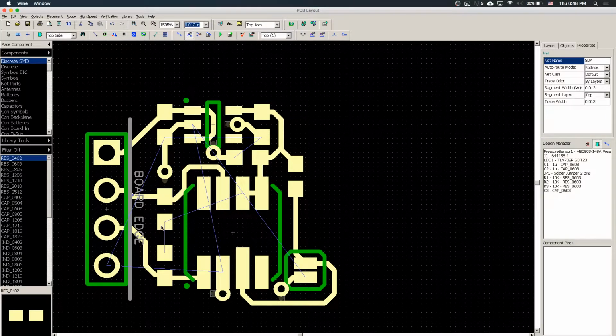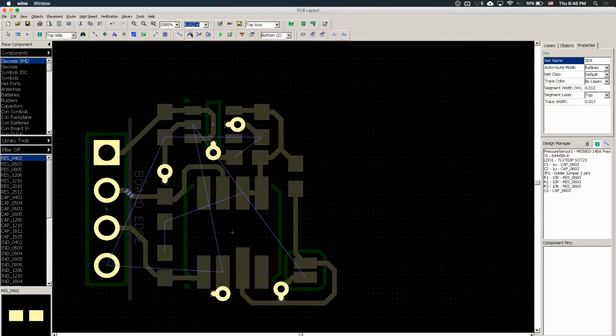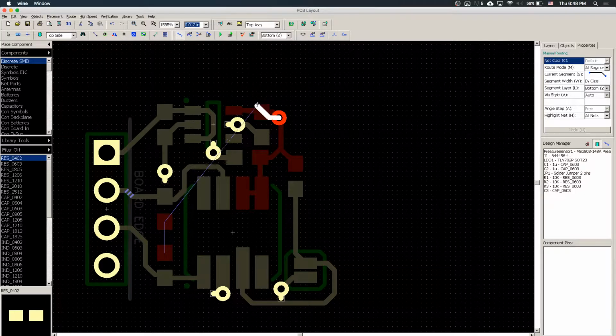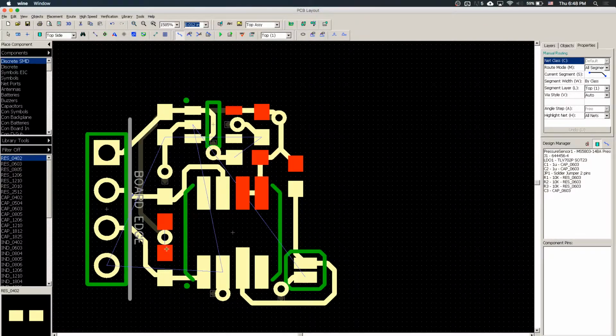And one last thing we need to do is connect the pull-up resistor with the VCC of the net. So we're going to use a longer via to do that. What we're going to do is start here and immediately put a via here and trace this back across our schematic, go back to here and go to the top. And then connect them all.